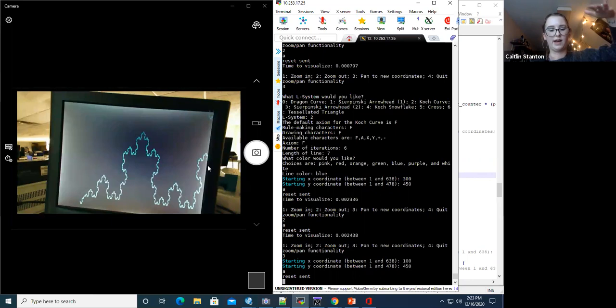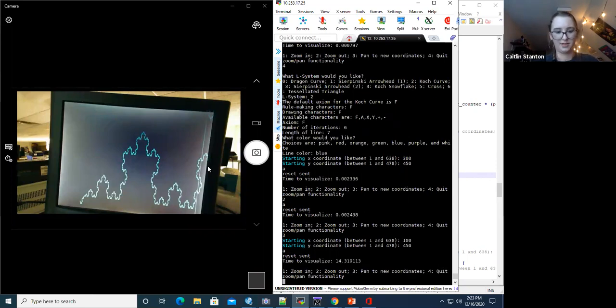So even though it looks like it graphed really nicely, because it's now in a negative number, it then becomes a super large 32-bit number. So technically what's happening right now is it's trying to calculate and graph stuff all the way below the bottom of the screen. So it's still doing stuff. It just takes a lot longer because the numbers are so huge. And then sometimes, in the cases where it does reach back to the X and Y values of the VGA screen, it'll draw a straight line, just because it wasn't expecting that number to be as large as it is. And so it'll just try to draw across the entirety of the screen. Yeah, so the straight line that I mentioned happened.